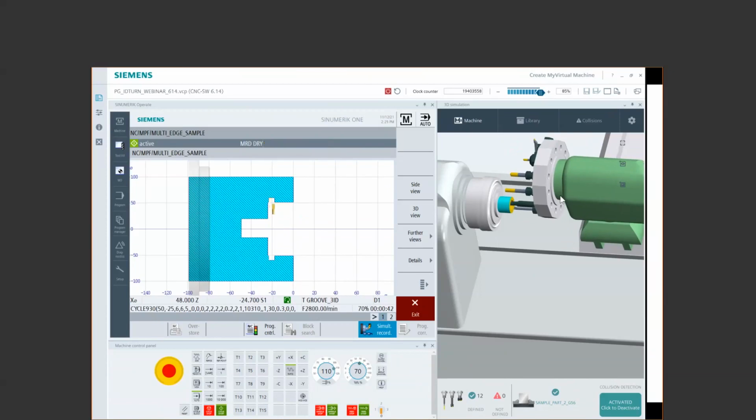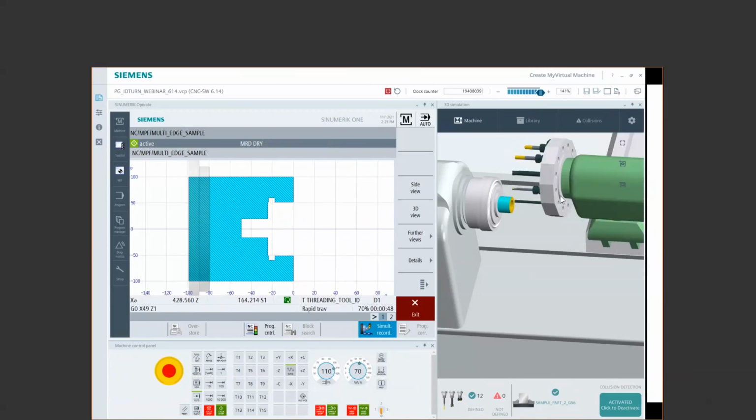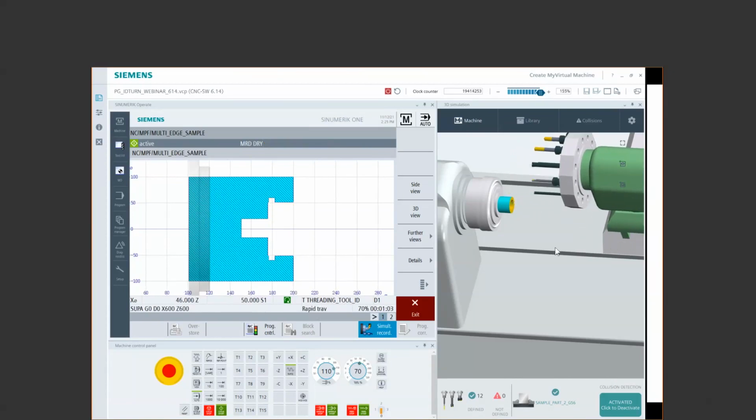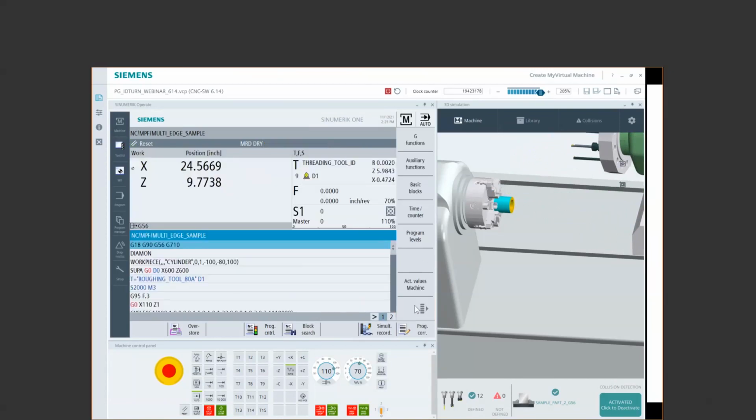Other ways to use cutting edges is maybe I had a little gang tool set up. So I have one bank that can do turning and maybe threading and grooving, which is pretty common. When you get to these turrets, you don't have a lot of turret locations, right? That's usually pretty limited. So you get somewhat creative as far as how you will set up these machines for sure.